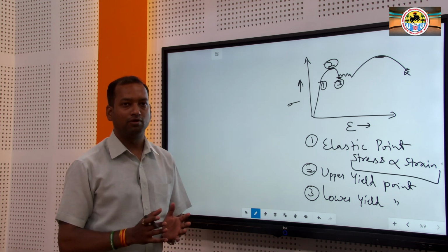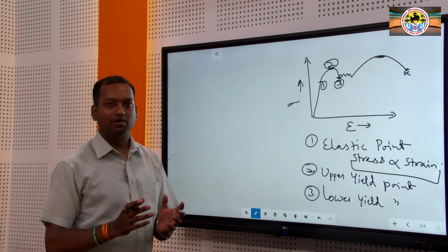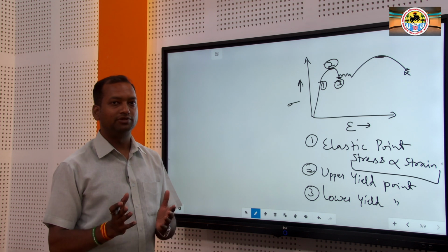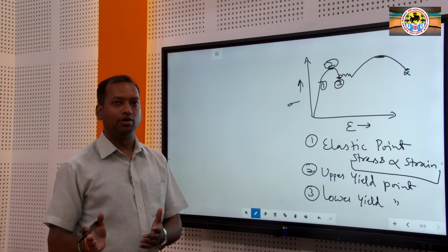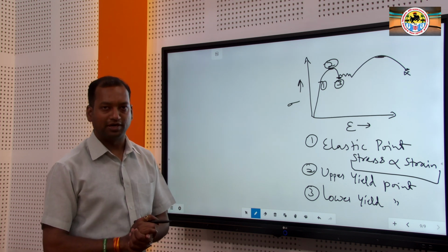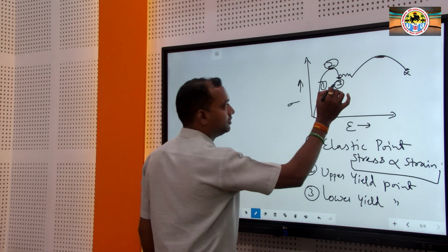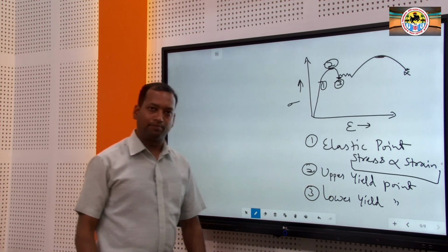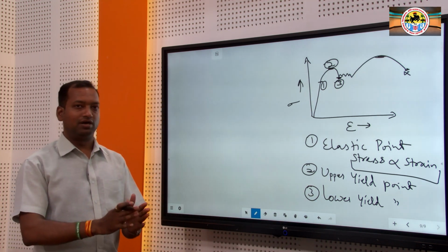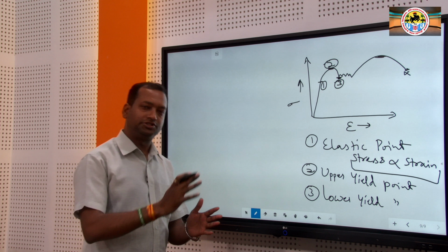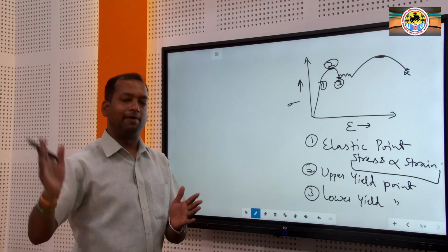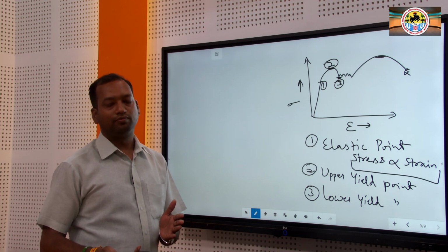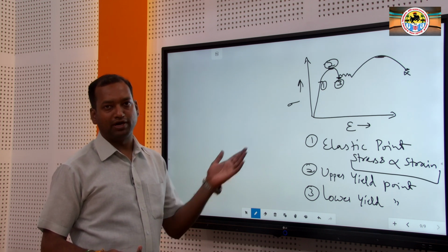As the bonding of these materials breaks, we are achieving our aim. Our aim is to go into the plastic zone, the plastic condition. So point number 3 suggests that the breaking will be there, and the strain level is going to increase even upon removal of the stress, or even if we apply lower stress than at point number 2.